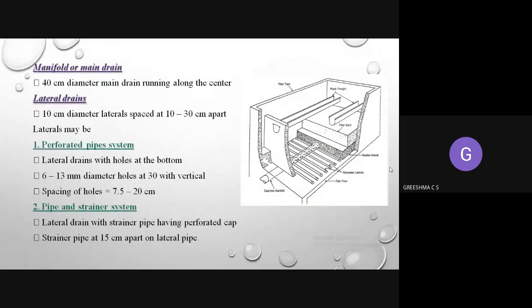In the bottom portion of these lateral drains there will be holes with a diameter of 6 to 13 mm, and a 30 mm vertical height.